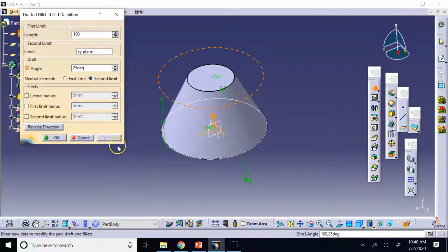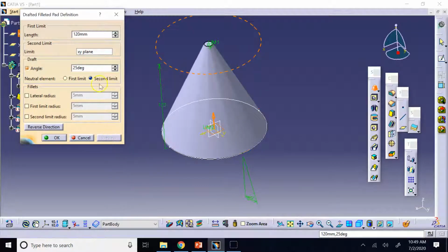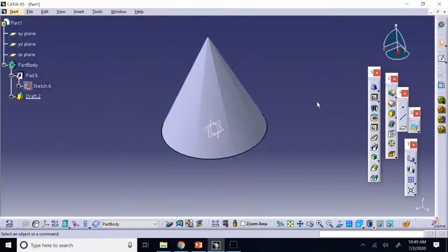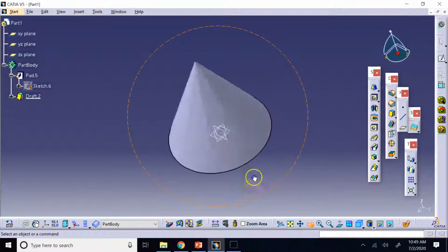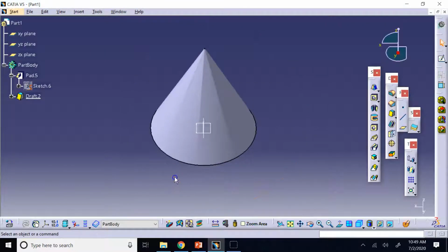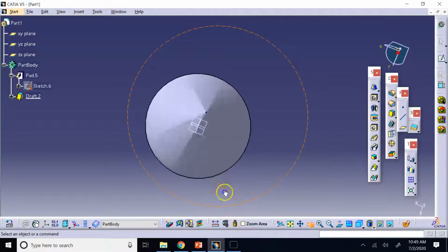So if, for example, I say here 100, still not enough, maybe 120 is more than needed, not even 130. You can mathematically calculate that, okay? And there we go, I got my cone. Now, of course, you clearly see that this cone, instead of being completely round, is like faceted, right? You can see different flat faces, and that is this performance that I told you.